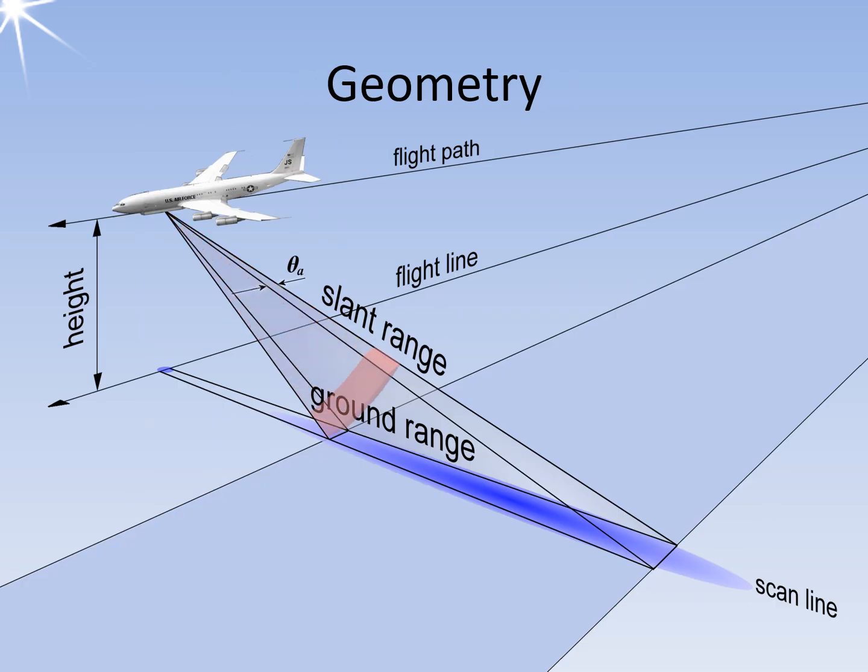As with any radar, the slant range r is not equal to the ground range. The ground range of the reflecting object is often denoted by the Greek letter rho. The received time-resolved radar signal contains information on the impulse response perpendicular to the direction of flight and, after processing, generates a line of the radar image. The processing of the next line in the radar image does not begin until the aircraft has flown a certain distance further. By repeating this process, a two-dimensional image of the radar pulses scattered on the ground is created.